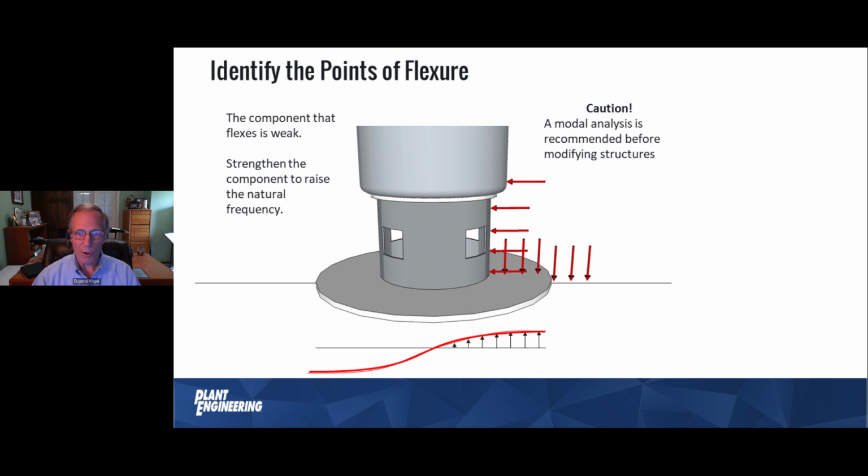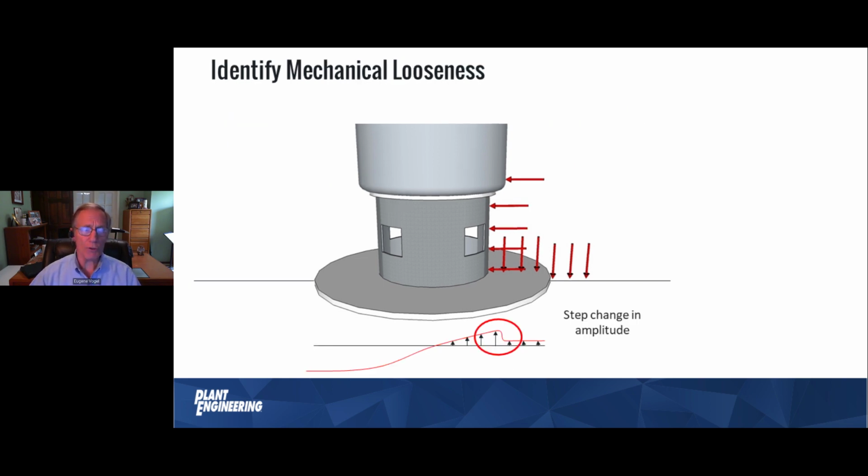We always recommend that before you do modifications, you do a complete modal analysis, because there might be another natural frequency in a different mode just lurking a little bit above that. You stiffen it up, you could hit that next natural frequency. So there's a little bit more there than we can get into, but just a word of caution. Although I've shown you something and said, hey, if you strengthen that base, you likely could eliminate the problem, I'm warning you, don't do that without doing a full analysis, because you get yourself into trouble with some other natural frequencies.